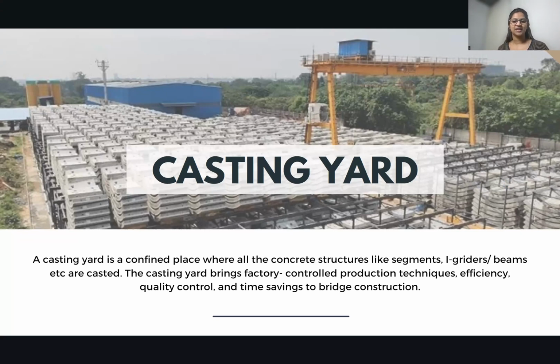A casting yard is a confined space where all the concrete structures like segments, I girders or beams, etc. are cast. So the casting yard brings factory-controlled production techniques, efficiency, quality control, and time saving to bridge construction. This is a pretty much self-explanatory definition, but I would like to give it to you in even simpler terms. Those segments are basically manufactured at this casting yard.